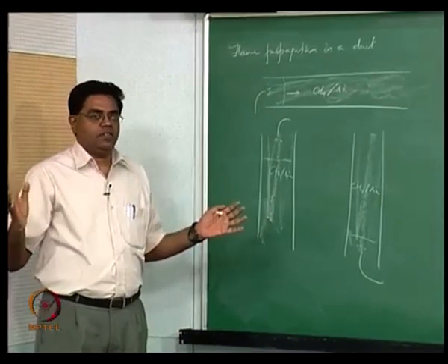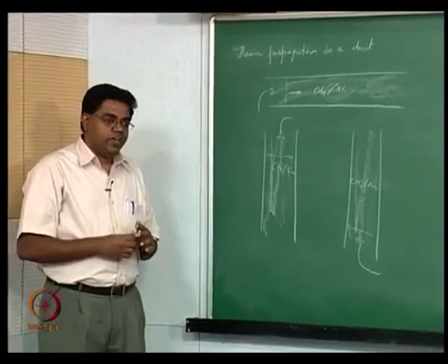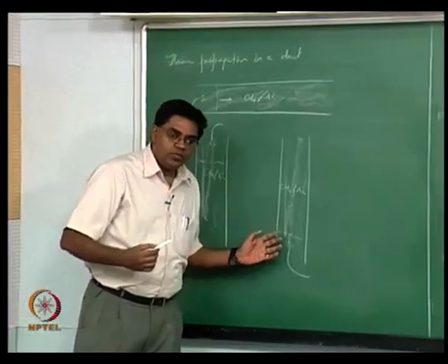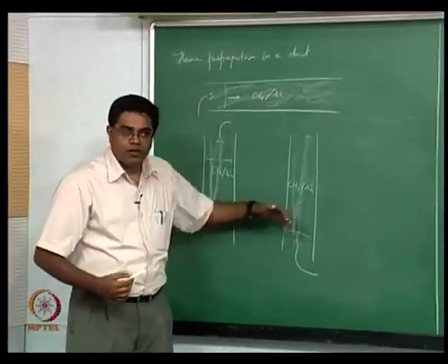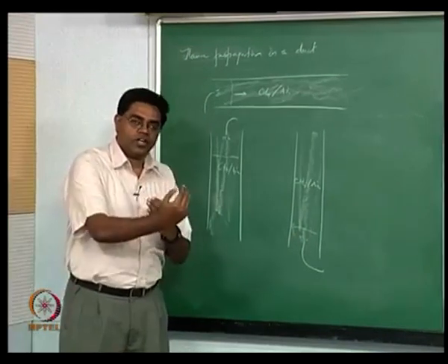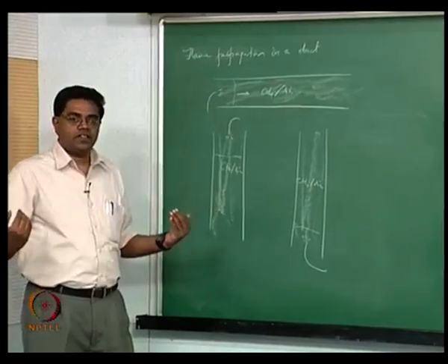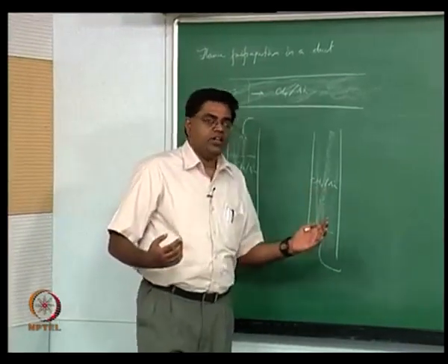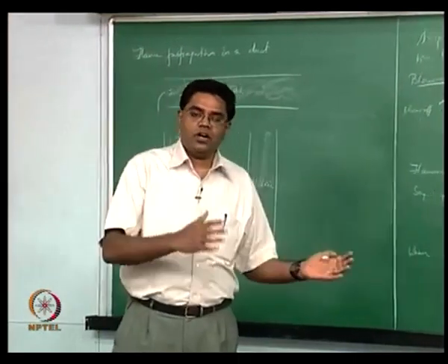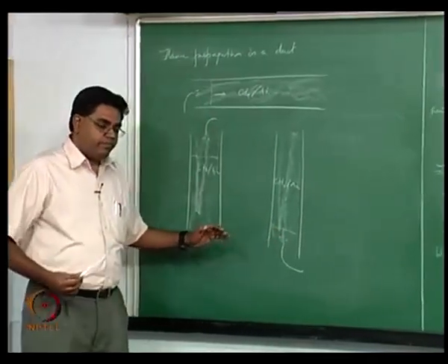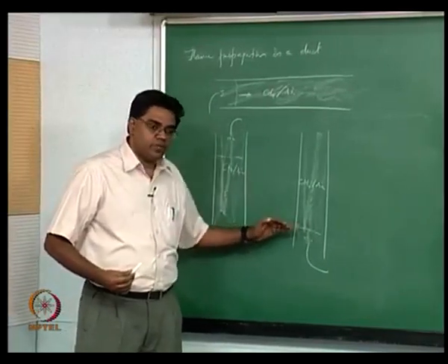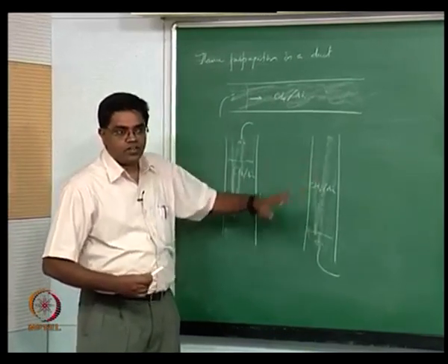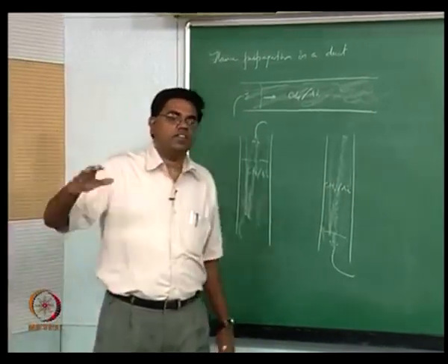On top of this, we will also have to factor in the fate of the thermal diffusive instability, that is like perturbation to a planar flame, and how much heat is going to get conducted versus how much reactant gases are going to get diffused, right, versus now product diffusion as well, and so on the one hand, and also the hydrodynamic instability of what's the fate of a flame that is perturbed from a planar condition with hot gases on one side and cold gases on the other side, where the density jump across this, you now have an instability because of that.